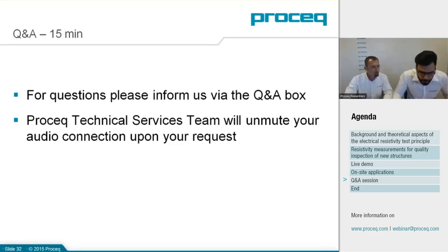Okay, thank you. What will be the standard moisture state of the sample to be tested? We talked about moisture, obviously it has an effect on it. You cannot define the actual amount of the moisture, can you? No, but you can define the curing. So we standardize the moisture by stating that the samples have to stay for a certain amount of time, either in a lime water solution or in a 100% moist room. And then you're ready to do the test.